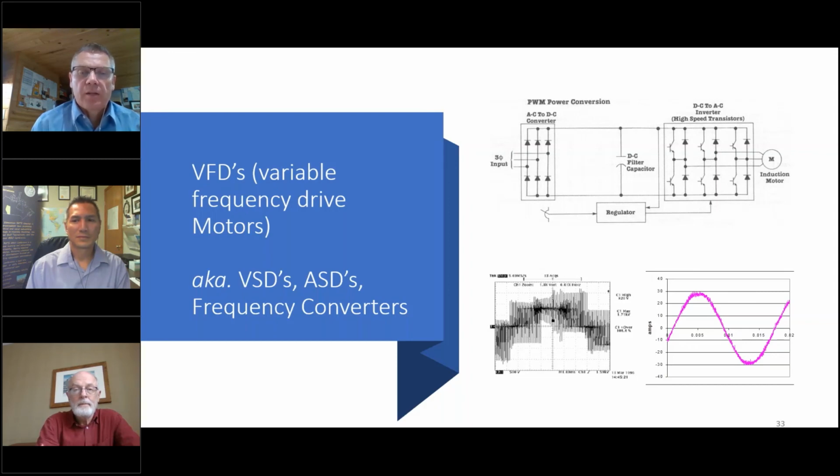You may have electrical failures on the windings because of contamination. There are a number of different maintenance things that you can do, and depending on the voltage, there are also some tests that you can do to look at partial discharge.